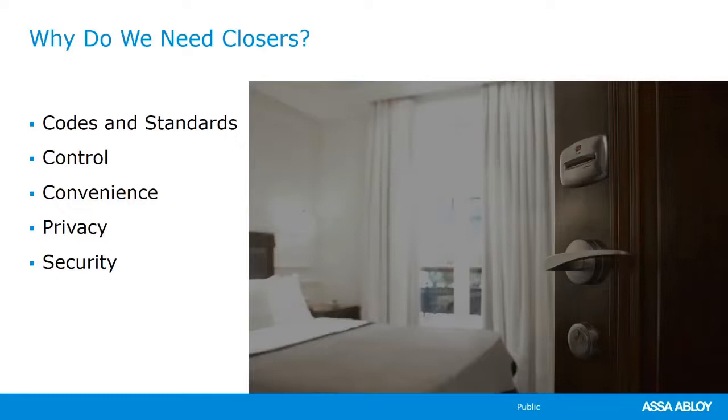And so we learned, or at least I learned then, number one, check your hotel rooms when you leave, make sure they're pulled all the way closed. But at the same time, the spring hinges that were on that door just did not have enough oomph to get that door pulled all the way closed. So I'm convinced that if it had a door closer, even a smaller door closer like the Norton 1604, the Yale 51, those are just a couple examples, even a smaller, less expensive door closer, I think, would have done a better job of closing the door than the spring hinges.